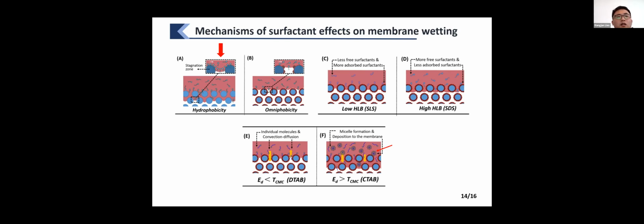In addition, according to the Young-Laplace equation, the LEP of the omniphobic membrane was enhanced by endowing the membrane with a higher water contact angle and smaller maximum pore size. All these factors contributed to the better anti-wetting behaviors of the omniphobic membrane.